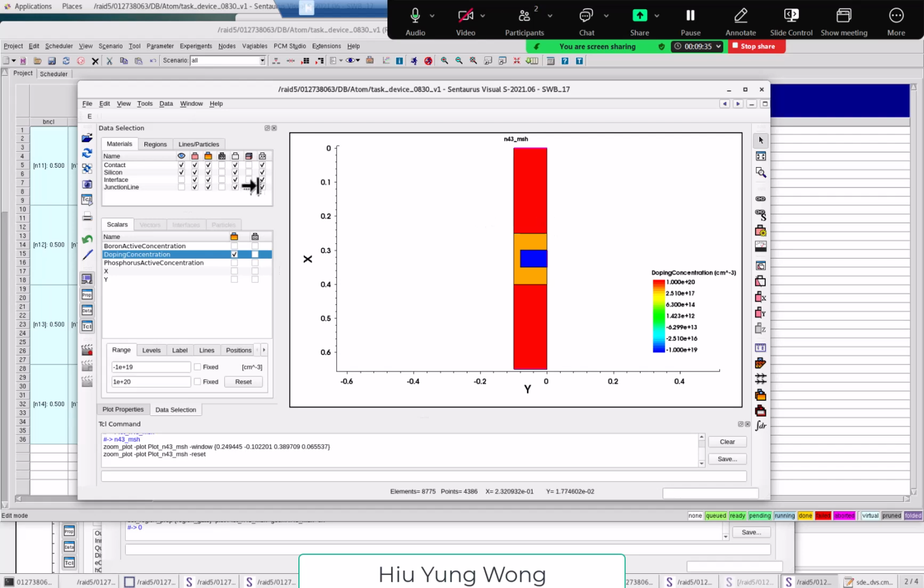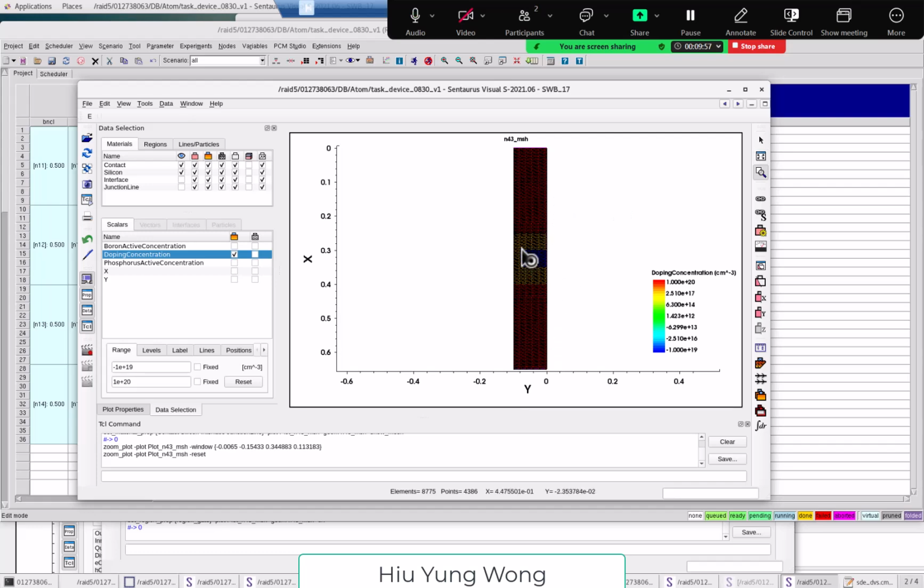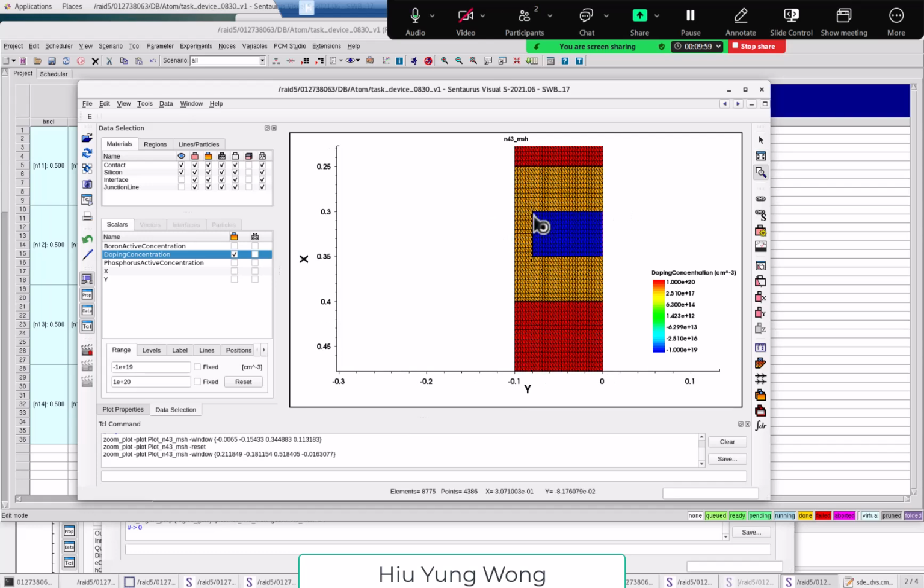if we look at the mesh, it's good, right? Now you have a good mesh. On the other hand, to make it more efficient, yes, it's good to add this mesh. I asked you to add a lot of mesh, but there is no need to be so coarse because we don't have a lot of physics going on here. So you can reduce the mesh in this region a little bit. On the other hand, you might want to increase the mesh at this region, not here, but here, even more, because at this region we have most of the physics going on. All the current is flowing here, right?